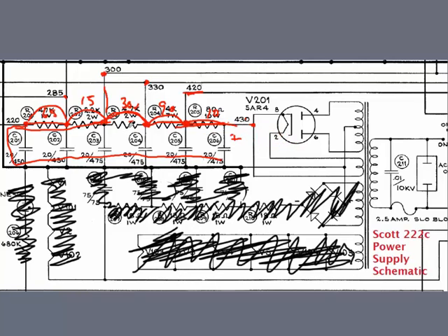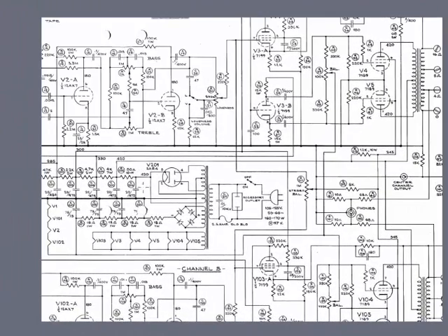But just to show you, this is a practical application of a voltage divider circuit. What they're doing with this, I'll show you here, is feeding different parts of the circuit that need different voltages. So this 420 volts right here, hang on one second. All right, I grabbed a little more of the schematic here, but right here's where we were, 430 volts, I'm sorry, and then 420 volts at this point. Well, that feeds up through here. Let's trace this all along.